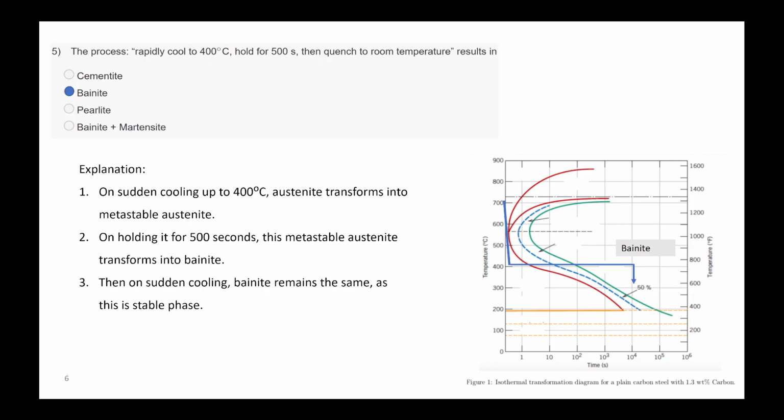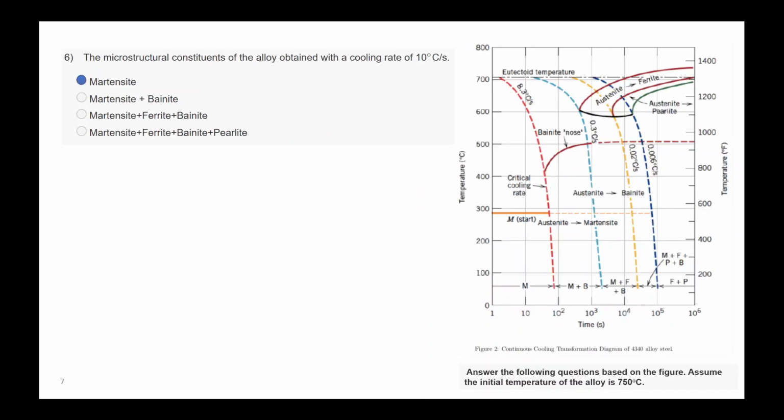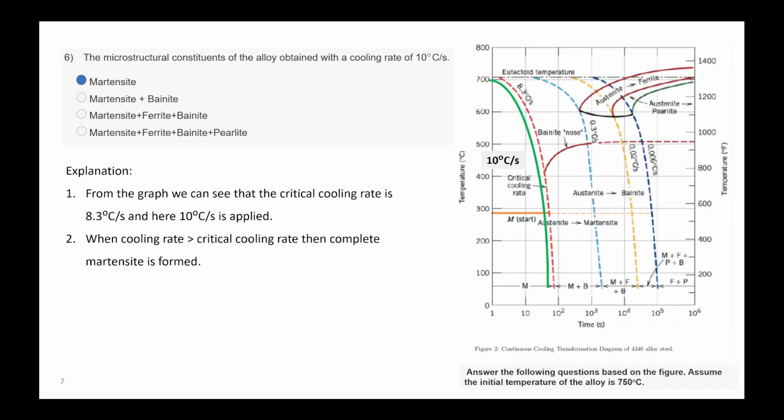Because the machine components that you'll be using in real life will always have certain defects in them. So in fracture mechanics, we will be considering the crack geometry and everything. Yeah, in fracture mechanics, you consider that there might be pre-existing defects. So you also assume what can be the critical size of that crack, and all those things you consider.